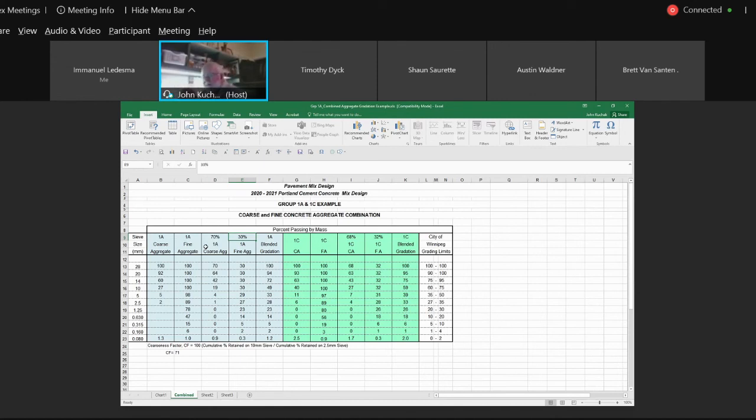Because again, many times we deviate from a standard, but we have to note where we deviate. And same with this. We might state that the aggregate does not meet the grading requirements specified by clause such and such, City of Winnipeg specification CW 3310-R17.